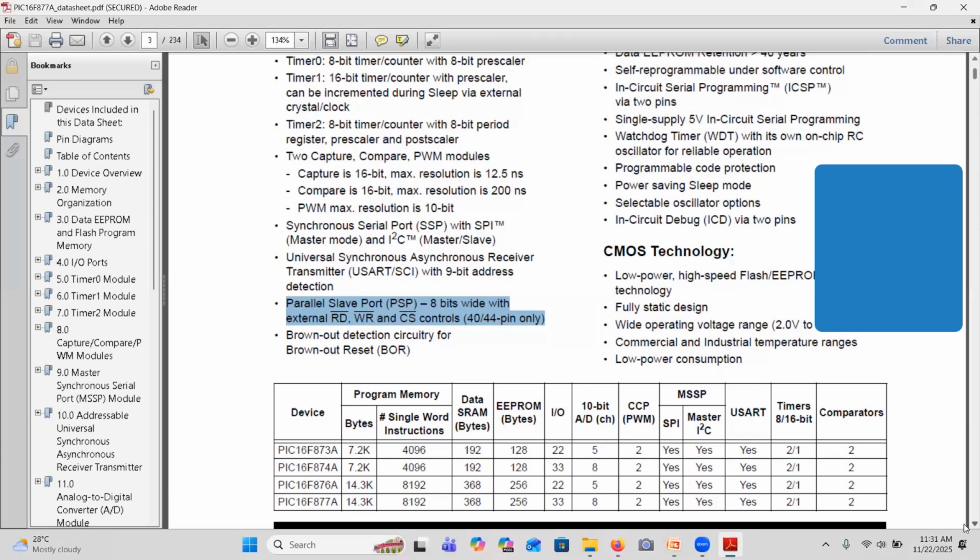See, say I have an application where we have multi-master, multi-slave related stuff. That means there will be more than one master, more than one slave. So that is a requirement of my project. In that case, the architect will decide, okay, it is multi-master, multi-slave, we can go for I2C. We can use the I2C of this particular microcontroller. But in my embedded project, I don't require it, there is no multi-master, multi-slave here. Everybody is master.